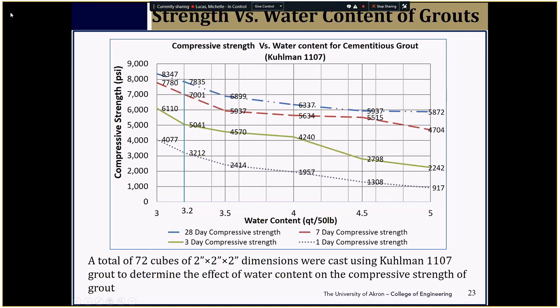What's interesting here is for the 1 day compressive strength, 3/4 of water, which is very difficult to work with, but in a lab we are able to control better, so we can make concrete with very low water cement ratio. So we got 4,000, which is not too bad. That's in a lab condition.